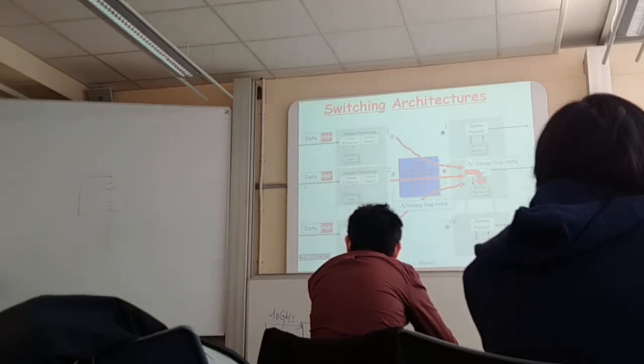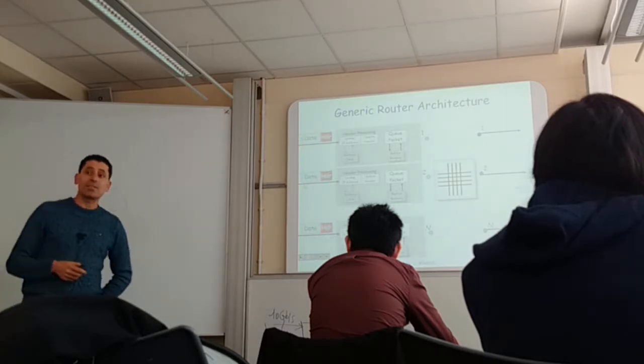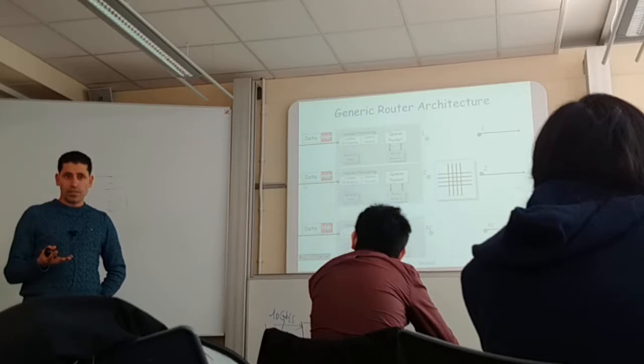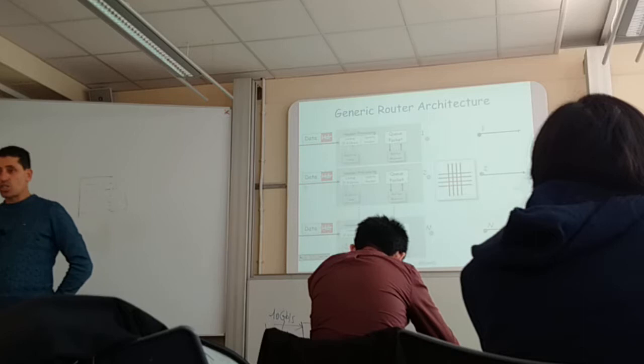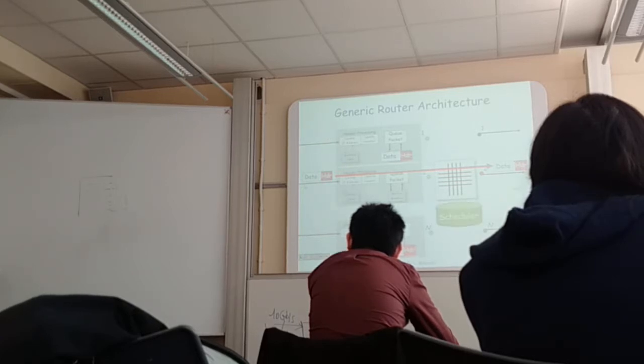So that's why the scalability of this memory is quite limited, because it's a function of 2 variables, the input line rate and the number of interfaces, whereas this one here is 2 times the line rate, and 2 is constant. If you see the difference. So 2 times the line rate is much more scalable speed-wise than n times the line rate, because it scales slower. So you can afford to have it faster at lower costs.